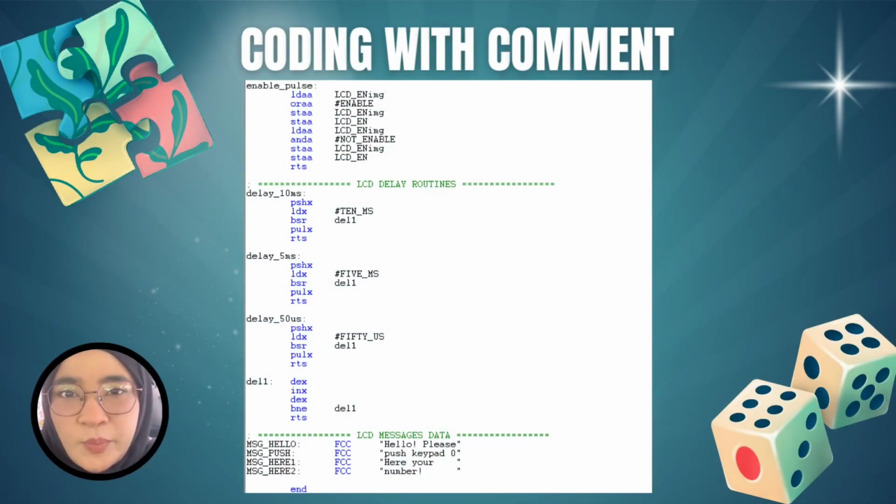Lastly, this part of the code is used to give a signal to the LCD, and also create small delays. The enable_pulse routine sends a short pulse to the LCD enable pin. This pulse tells the LCD to read the data that was just sent. First, the code turns the enable pin on, then it turns it off again. This on-off pulse makes sure the LCD accepts the data correctly.